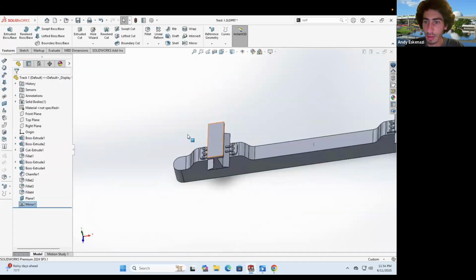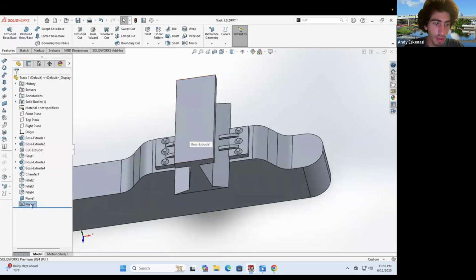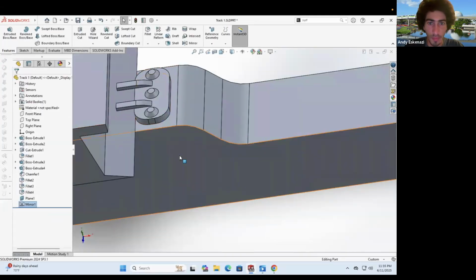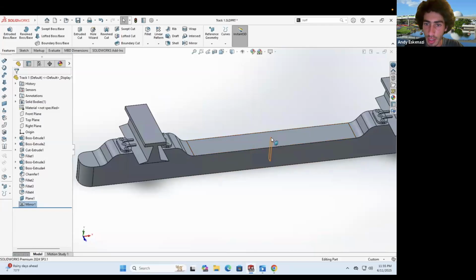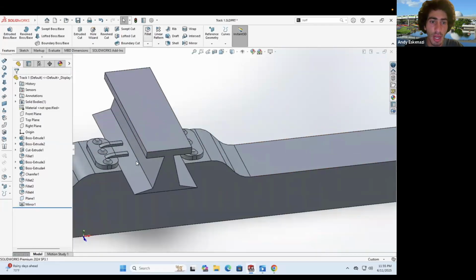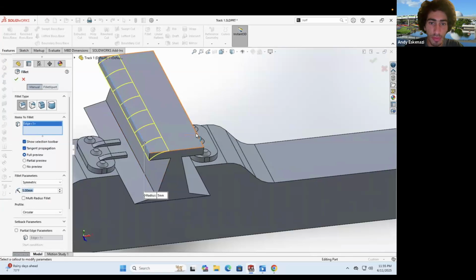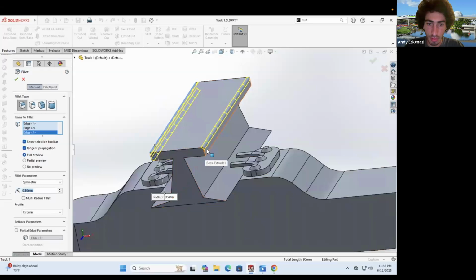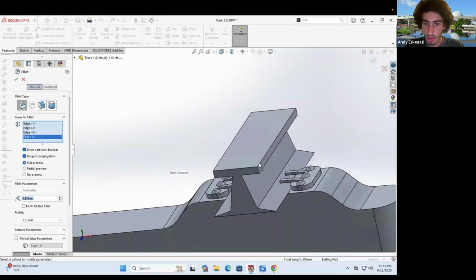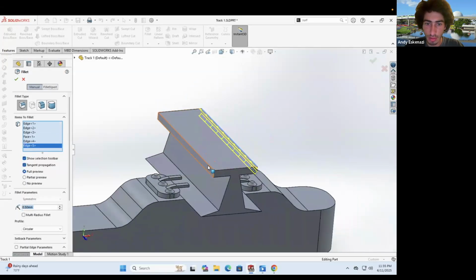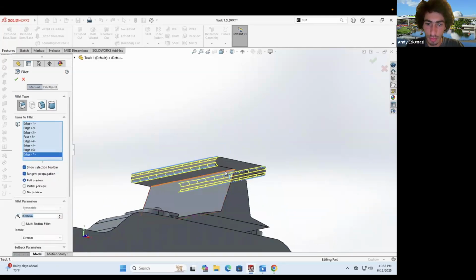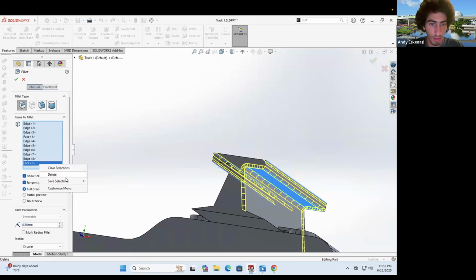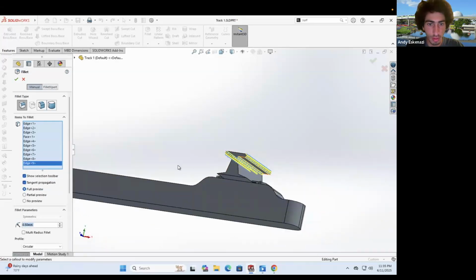And now I'll mirror through that plane. Features to mirror. I'll do, well, all of this. Let's see. Does it work? Oh, maybe I forgot the fillets. There we go. Okay, perfectly. And now I can hide that. And then perhaps the last thing I'd like to do is give that a 0.5, both over here, over there, over here, over there, maybe, oh, not there, certainly here.